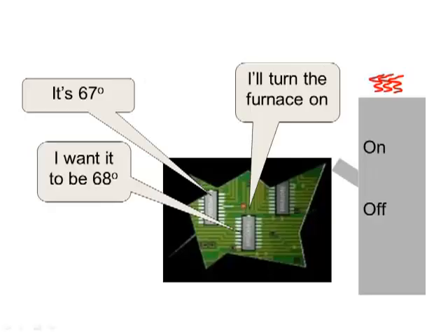So first, what do we need to understand about this system? Well, we know that a thermostat controls a furnace. If the temperature is too cold, that means below the point where we set it for, the furnace should turn on, and if the temperature is warm enough, the furnace turns off. So it's just fully on or fully off, okay? Contrary to what some people believe, you don't really control how much a furnace comes on. It's either on full blast or it's off, okay?